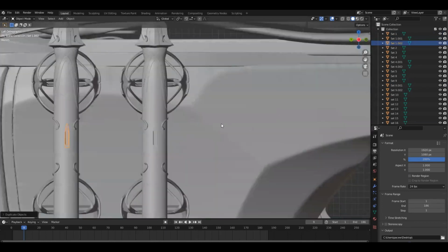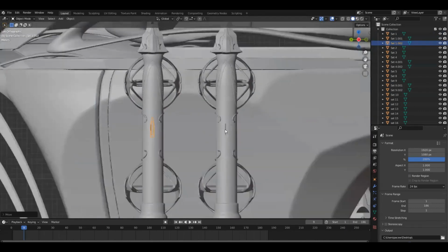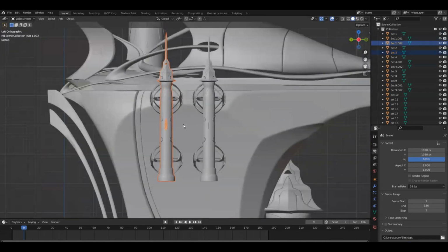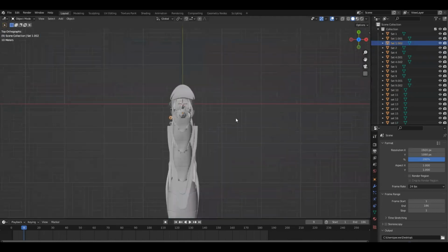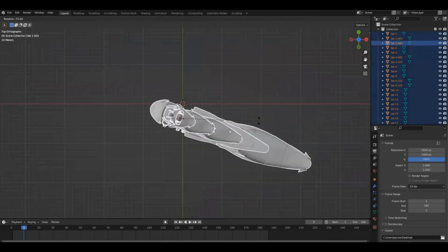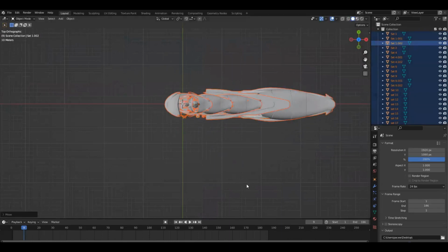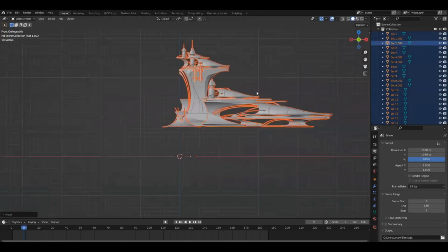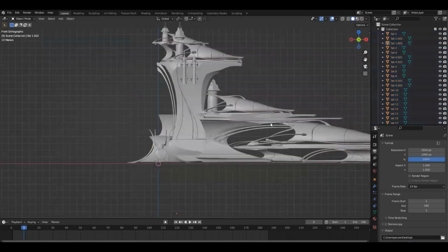And from the view, I was just trying to see it from the front view just now, but actually this all imported at a slightly different angle. So I'm actually going to hit A to select all. And let's see if we can rotate this by holding the Control key to snap to segments. I'm going to get it so that when we go into front view, we're seeing the actual front of everything. All right.